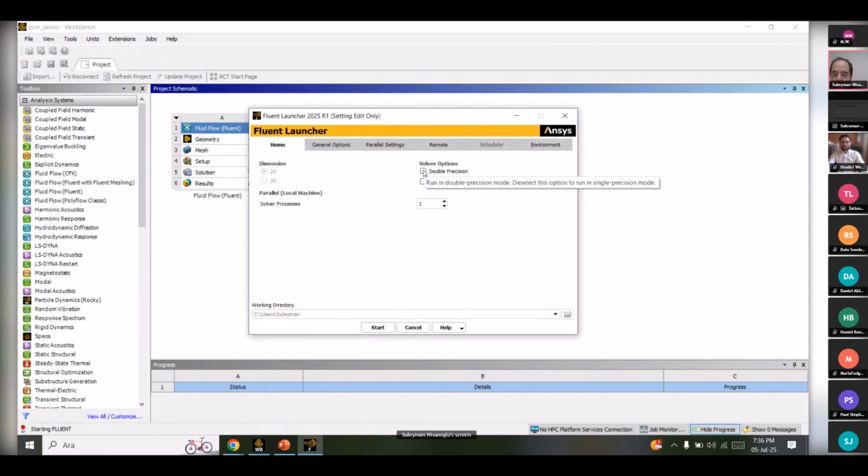And first of all, when we open the Fluent program, it asks us how many processor cores we want to use. Here, processor, I select 4. For the student version, maximum 4. Let's set our core count. Also make sure to check the double precision option here.